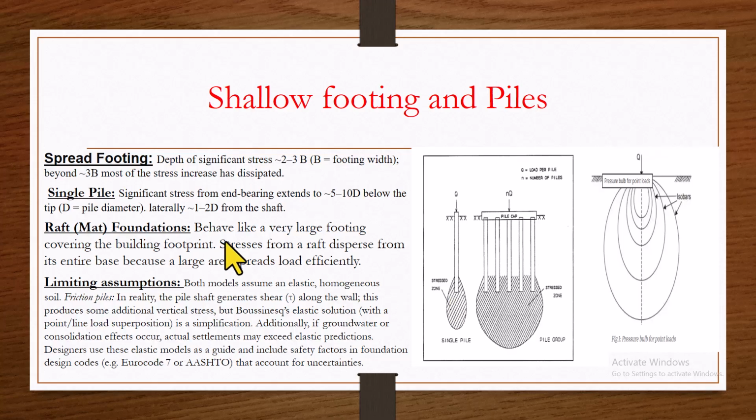And that is why in your pile foundation, the recommended depth is always 2.5 D and above. That is the spacing between your piles, whether they are in a group or not, the spacing should not be less than 2D. Because once the spacing is less than 2D, your piles will begin to interact.